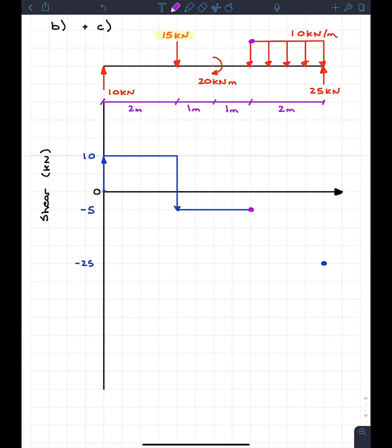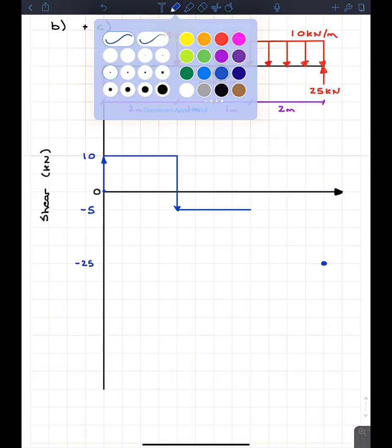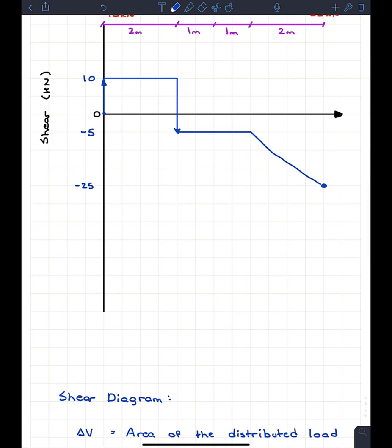So I look up here, my distributed load at that same point is 10, or negative 10. And if I look at this point at the very end over here at x equals 6, my distributed load has the same value, 10. And throughout x equals 4 to x equals 6, it always has that same value of 10. So between those 2 points, my shear is constant. If my shear is constant, it must be linear, like this. Oops, I used the wrong color. So it just goes directly from those 2 points in a linear fashion.